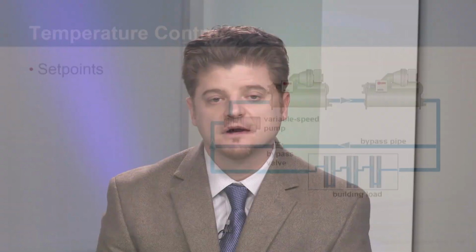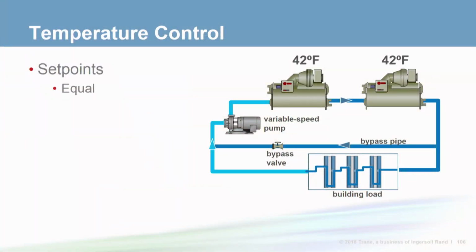In addition to reduced chiller pressure drop, a variable primary flow system helps with set point control and upstream chiller efficiency. Temperature control can be executed in several ways. The image shows a strategy where the controller on each chiller is set at the system design set point. In this layout, either chiller can be used to meet the system demand for up to 50% of the system load. As system loads go greater than 50%, the upstream chiller is preferentially loaded because it will attempt to produce the design leaving chilled water temperature. Any portion of the load that remains is directed to the downstream chiller.